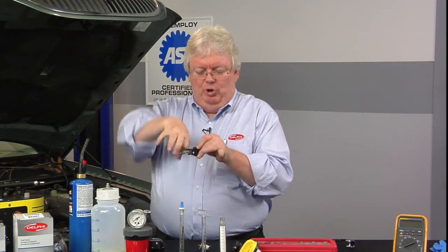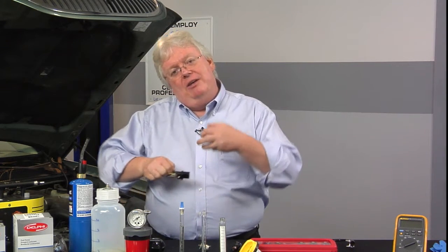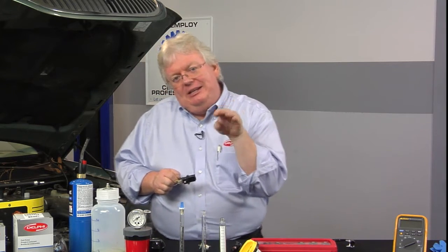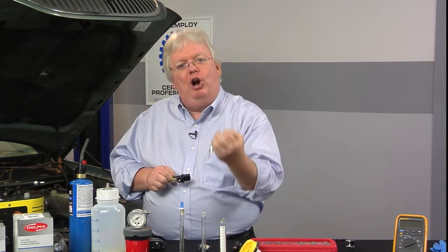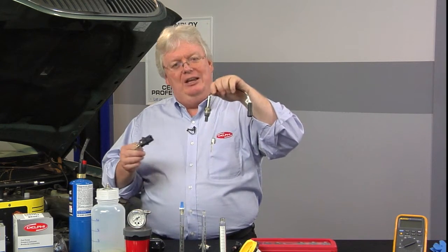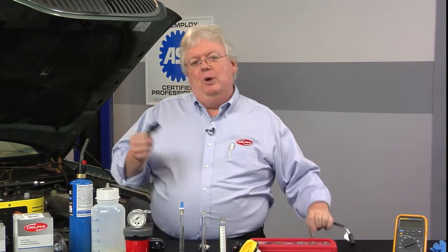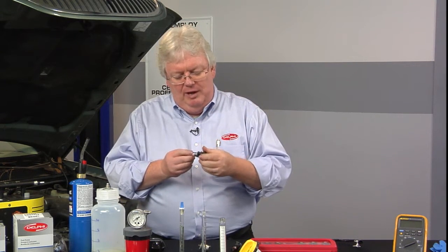micro amp clamp to go around inductively around a wideband or air fuel sensor, and then hooking that into their lab scope and seeing those positive and negative current patterns, and making decisions like we did early on 30 years ago with the switching style O2 sensors, watching those with scan tool graphing and scopes. So I anticipate maybe in the future we may do a wideband and switching O2 sensor program, but for now that's a little high-end overview of these sensors.